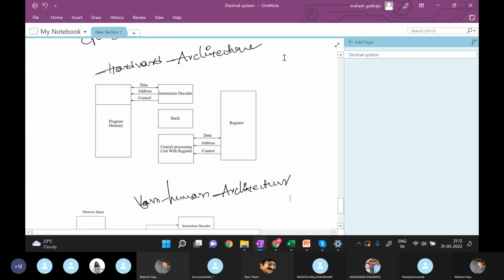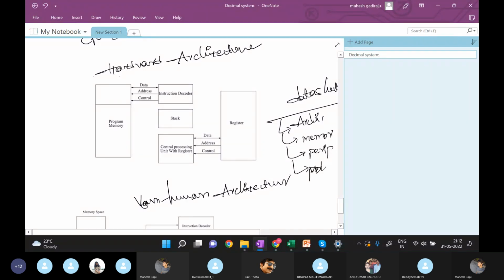Each and every microcontroller will come with a data sheet, which will have all its properties: what kind of architecture it has, what kind of memory, what peripherals it is going to support, the voltage levels, power supply ranges, the pin configuration, and what kind of interrupts it will support.